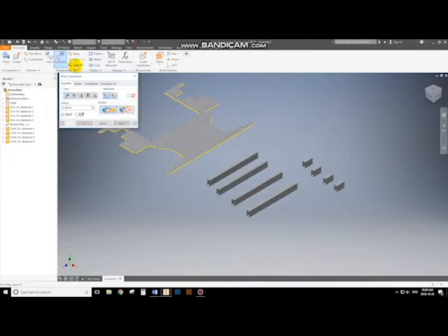Constrain is the most useful command for making assemblies. Most of creating assemblies is using the constrain command. Learn to use it, and use it well. To constrain a part is to determine where the part is in relation to another part. This is how we stick parts together to create an assembly.